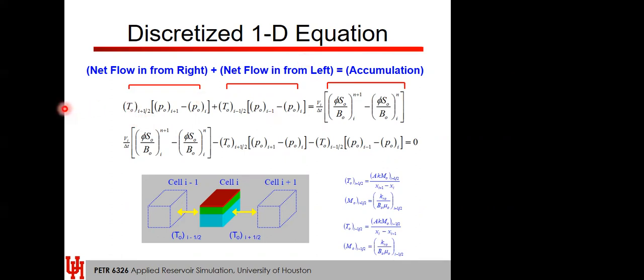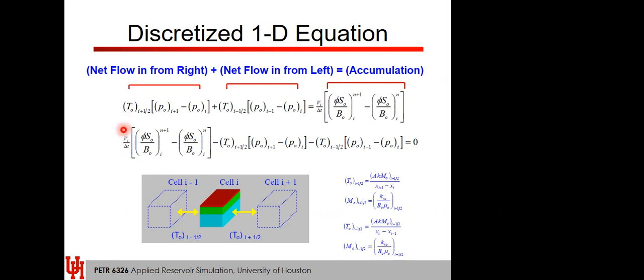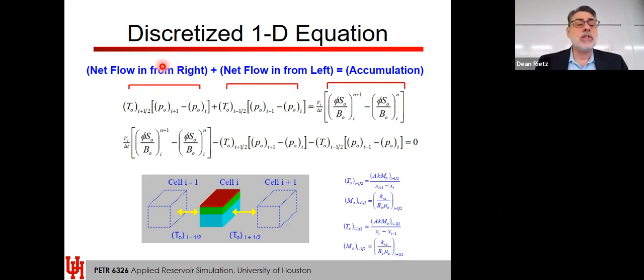Yes, so just to compare what was just said, transmissibility is the value between two cells, right? Correct. Center to center. And the pressure that you've indicated is what? So this pressure is the cell block pressure from one time step to the next time step. So this is I plus 1 and I.